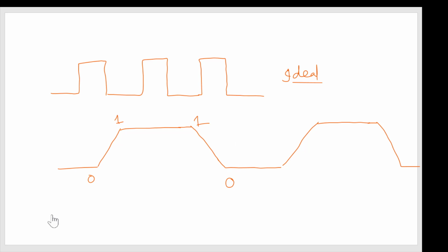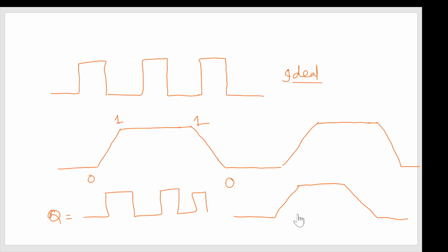Similarly, whenever the clock output, let's say you are having Q output for a flip-flop, it will not go like this, 0 to 1 or 1 to 0. It will also go in the same fashion, 0 to 1 and 1 to 0, and so on. So there is a delay from going from low to high to low. This you have to consider when you design a practical digital circuit based on the flip-flops. Now we'll see what are the parameters one should consider for this clock signal or for this data signal.